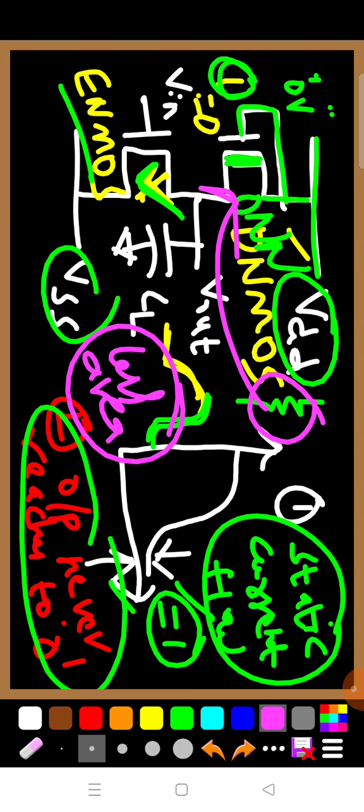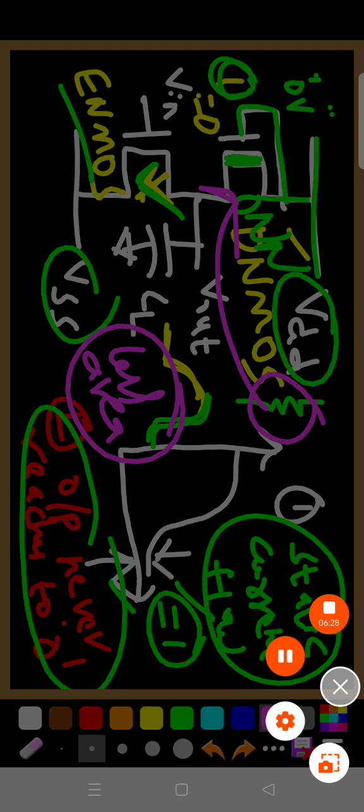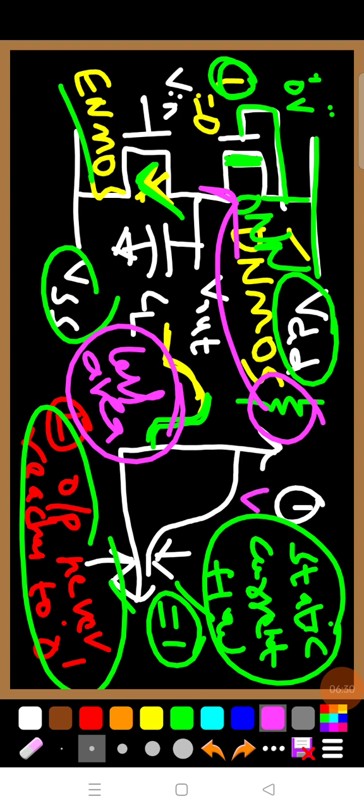That's it, guys. This is about the NMOS inverter. After this we will discuss various pull-ups. In these various pull-ups we will try to understand, but don't forget, the drawbacks still continue in this NMOS inverter: static current flow and output never reaches 0. We will see how these drawbacks are going to be overcome.